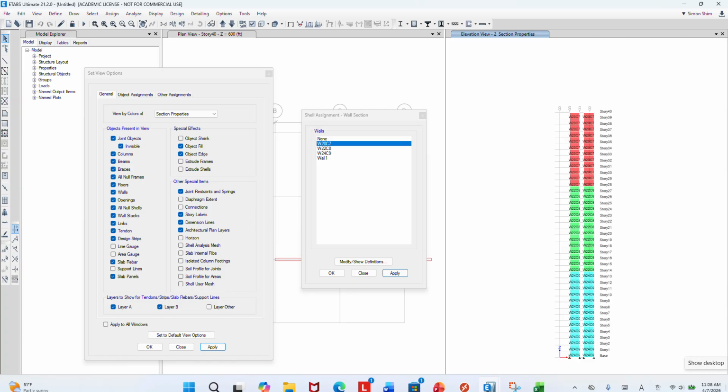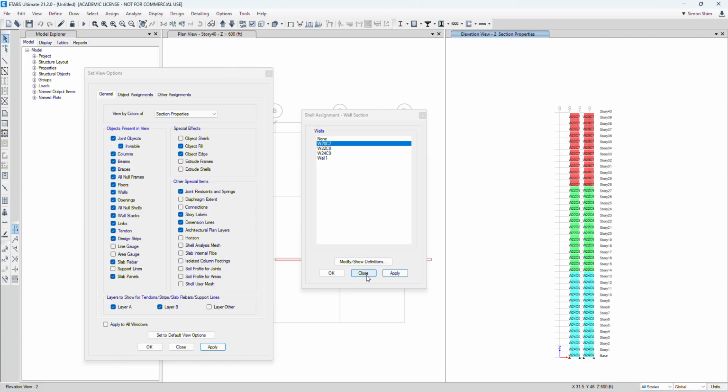You saw that you need to have more stiffness. Lateral stiffness will be a cantilever. Now one way to scale up is you need to assign a thicker wall. Right? And using higher concrete strength, right? So this is the example of the procedure of stiffening.